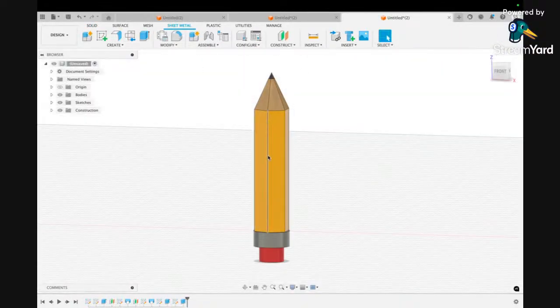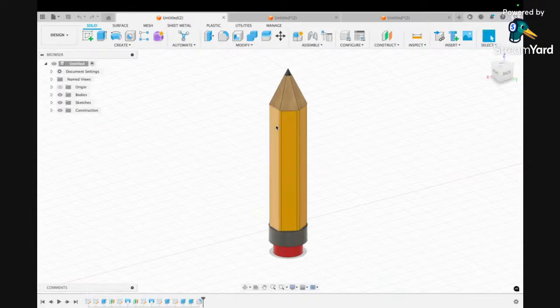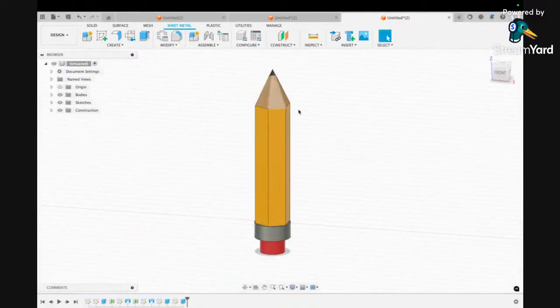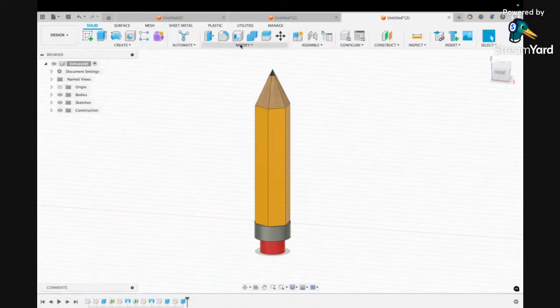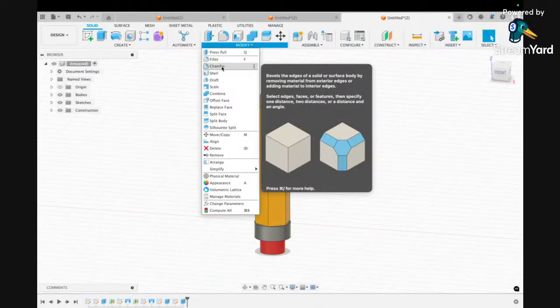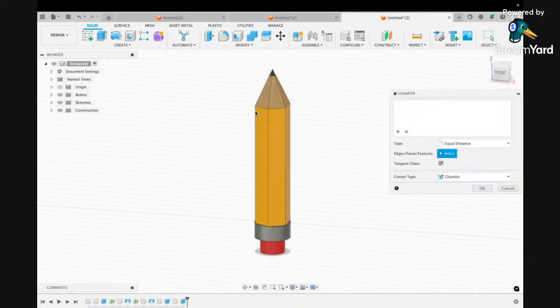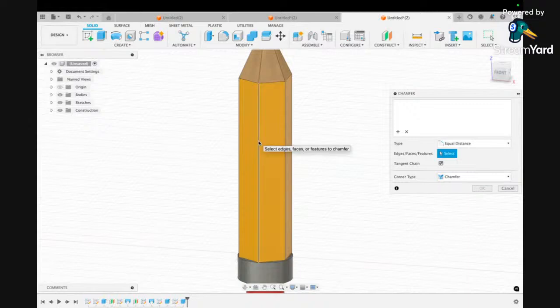That's perfect. The edges, as you can see here, there is no curve or cut in the edges, but here there is a small cut in the edges. So this also I'm going to tell how to do. It's a very simple task. We just have to go to Solid, Modify, and as you can see, there is a chamfer tool here. This is also a basic tool that we use often. Click on that chamfer tool and select the edges, these lines. Select all of the lines.